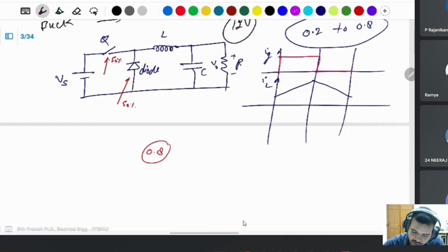The switch is on for more time, and the off time is very small in this scenario. At that moment, this switch is on for a very long time, and the diode works for a very small amount of time. The power losses are different for both. One switch heats up, the second does not heat up, because of this only. One switch has more power dissipation, and the diode has less power dissipation. Then you should choose the switches accordingly for operating this.